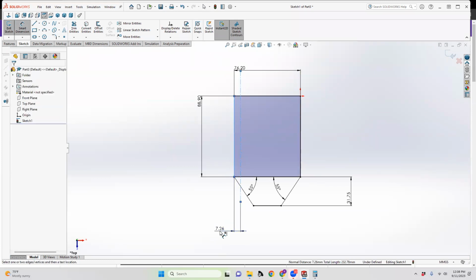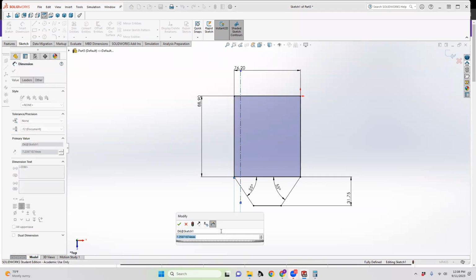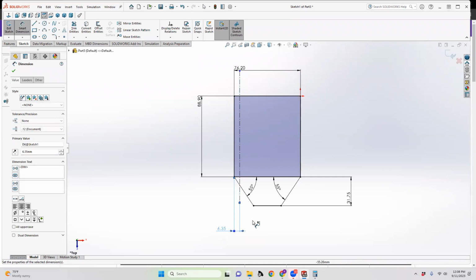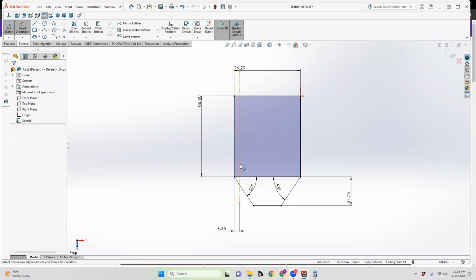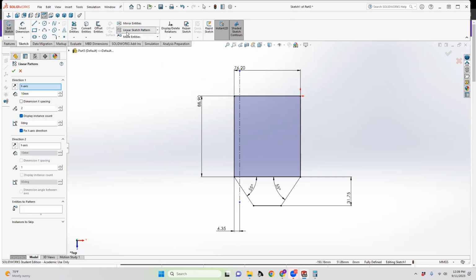Some of you won't think SolidWorks is cute after today, but that's okay. You could say 0.25 inch. So we're pretty close to there. You can do a pattern. So it's called a linear sketch pattern. So there's a couple different variations. You'll use the circular sketch pattern in the tutorial. We're going to look quickly at this one.